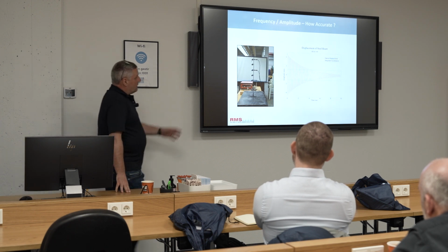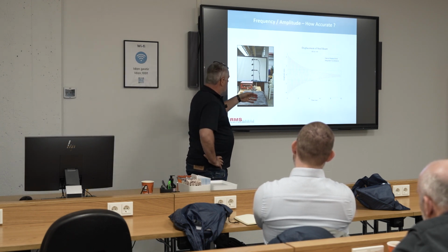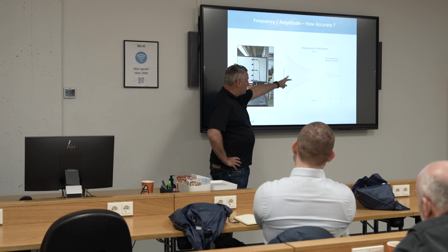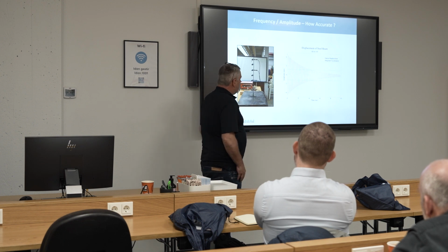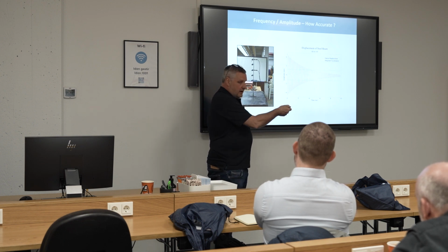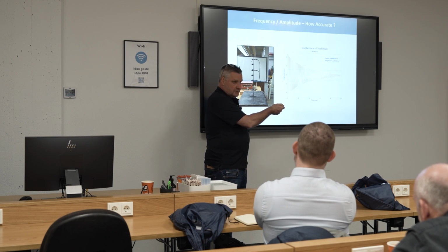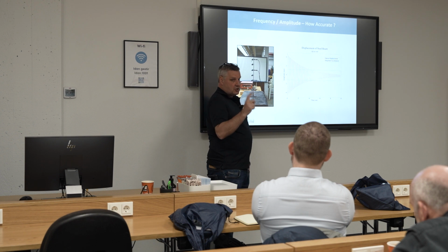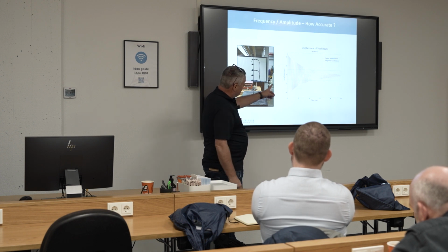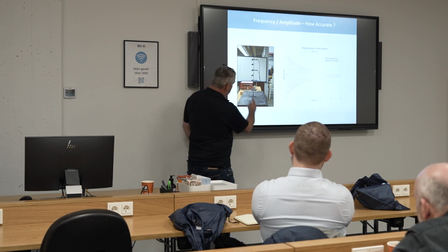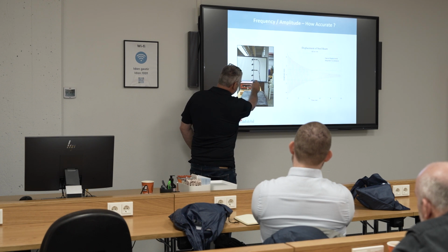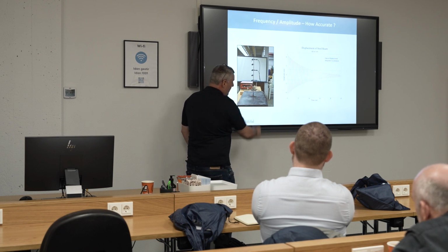We tried to make sure that the amplitude coming back off these videos is very similar to what you get in a vibration test. It's important, and it's relative to the distance you're away from the actual component when you're measuring it. We have a laser, and we take a distance measurement off the laser to where the camera lens was to the component, because that's critical. That distance is critical in giving accurate amplitudes back. And we did tests with, like you said, a thin plate, where we impacted and resonated off the 4 sensors, and we put 4 ROIs on there.